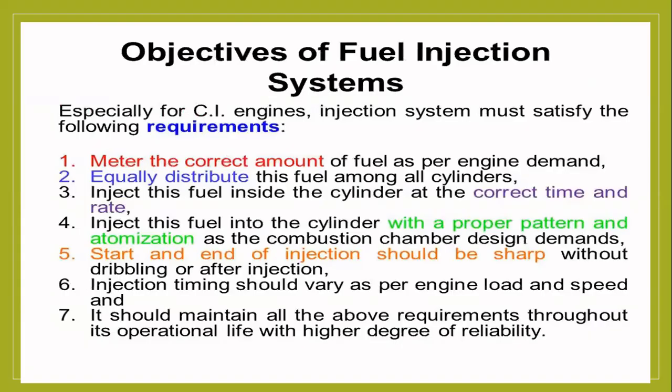Objective of the fuel injection system again: meter the correct amount, equally distribute, and inject fuel inside the cylinder at the correct time and rate with a proper pattern of atomization. Start and end of injection should be sharp, right? So injection time should vary per engine load and speed. Yes, injection timings should vary.